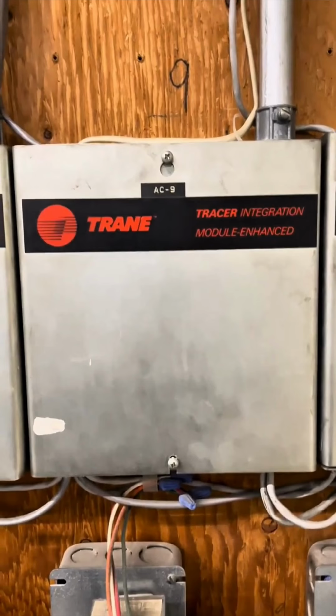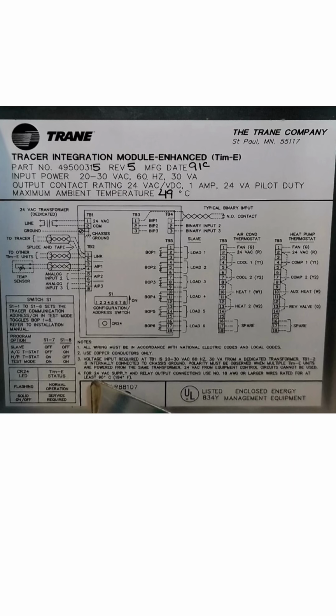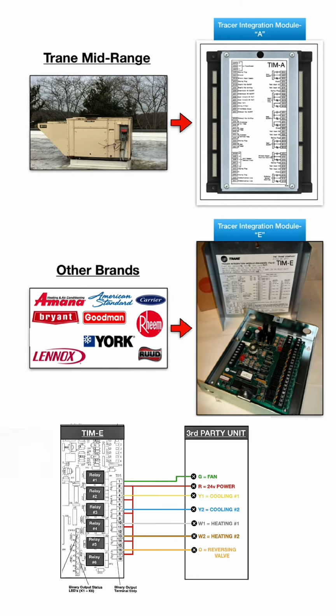Then came the TIME, or Tracer Interface Module Enhanced, which emulated thermostat logic to integrate third-party equipment into the Tracer 100 on the standard thermostat terminals, R, G, Y1, W1, etc.